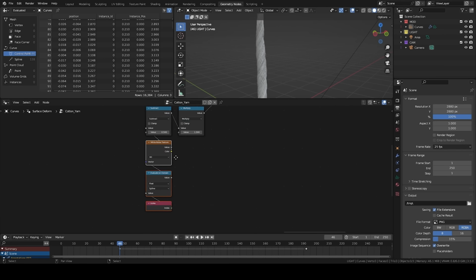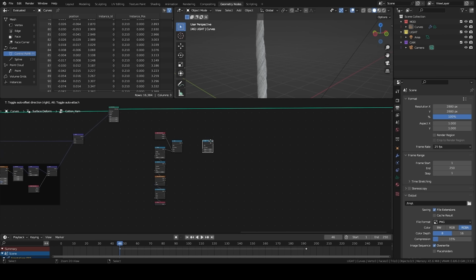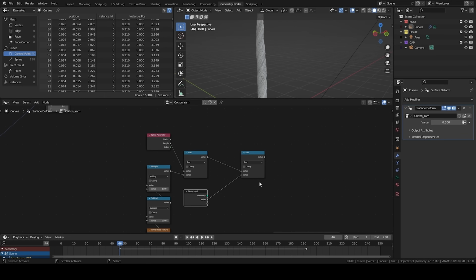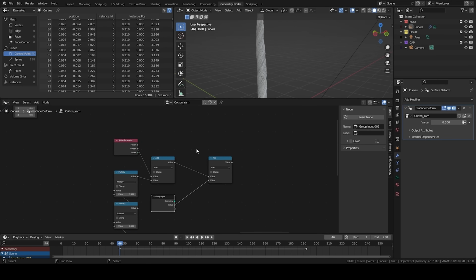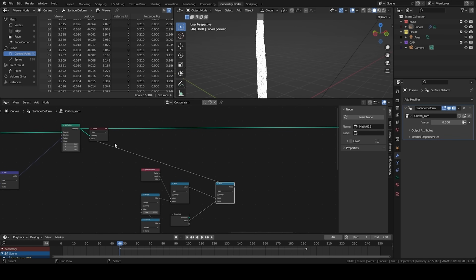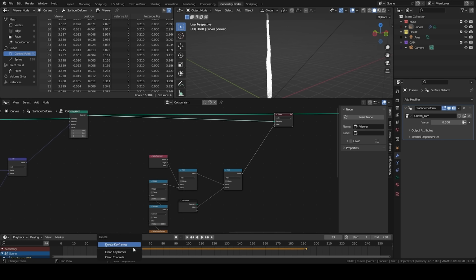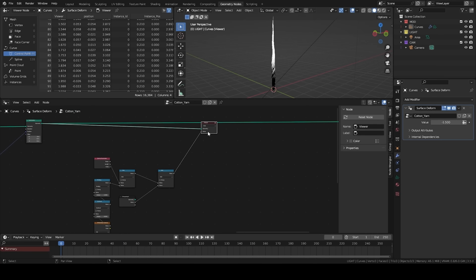That way, if we wanted to save a little space, I'm going to add a second add. And this time, it's going to be something that we're going to control with a group input. There, I'm going to promote the attribute, at least this little parameter, in my group input. And I can find it now here. It was named value. I can find it right here. If I look at it, normally I'm supposed to be able to create a black and white gradient with this attribute, and it's the one that's going to help us control the rotation and the flow of each spline. We can animate that by hand as well, and we'll be able to see that later. I'm going to leave it a little more, halfway up, and we'll see what happens.